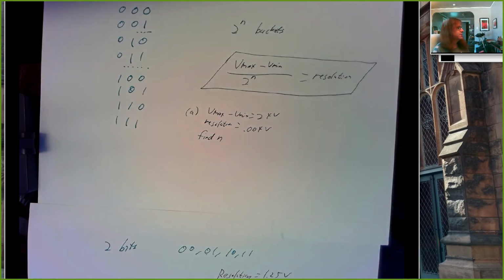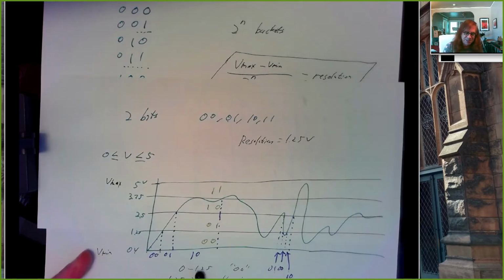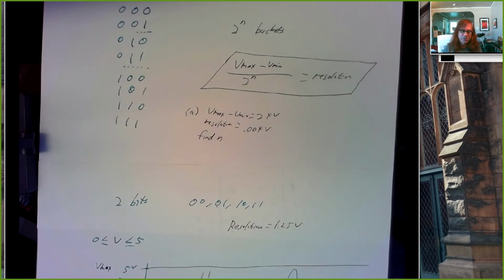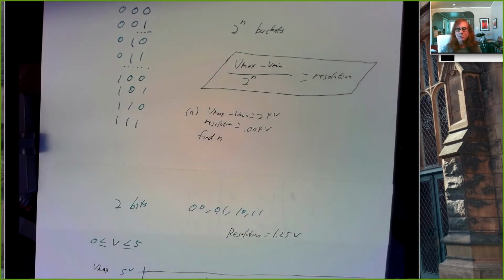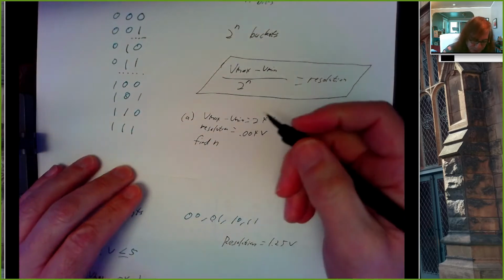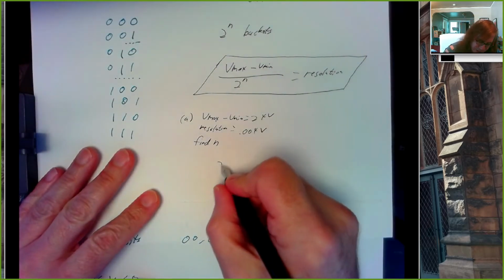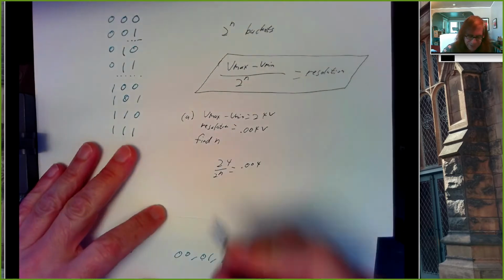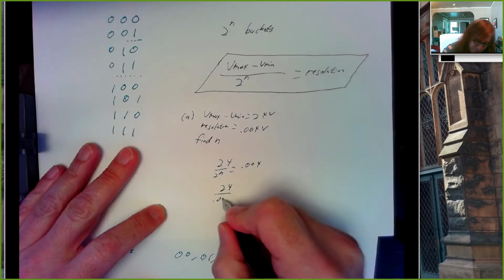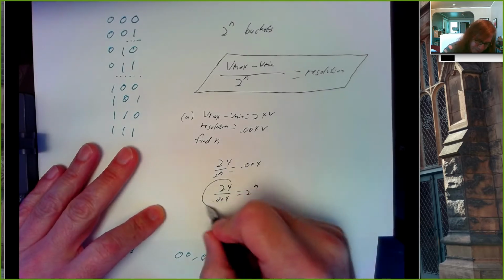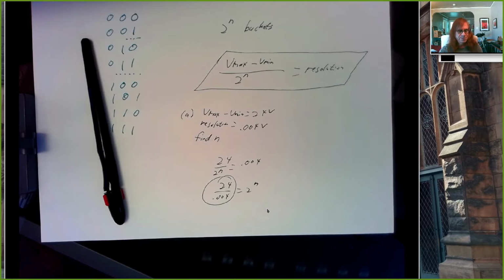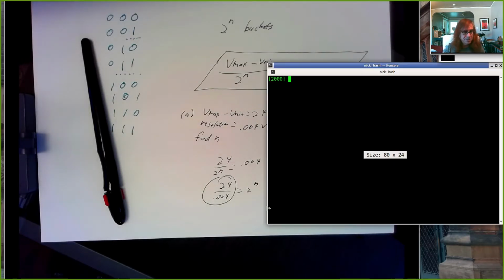So resolution of least significant bit, that basically says, if we change 1 bit, the rightmost bit, we want that to correspond to a change of 0.004 volts or better. So we want to find an n, so you basically plug in 24 over 2 to the n equals 0.004, and flip it around, 24 over 0.004 equals 2 to the n. Find what this number is, and now you're back to one of those earlier questions about works of art and trying to store them using bits.